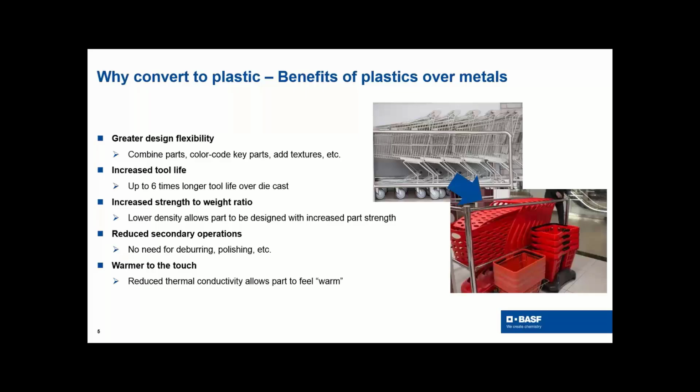Increased tool life. Injection molded tool life basically is longer than a die cast part, and it's up to like 6 times longer. So that's a nice little benefit. Increased strength to weight ratio. In general, plastics are not as strong as metals, but because of the lower weight, we can design it and make it stronger. And we'll see that in some of the slides coming up here.